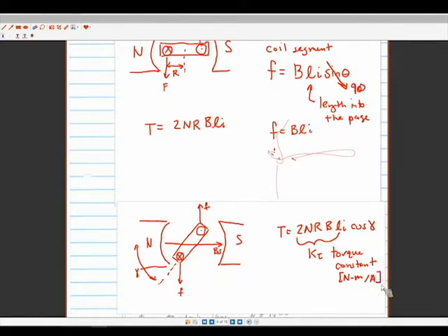Okay, so what the torque constant gives us is basically the relationship for a given motor, it gives us a relationship between current put into the rotor versus torque produced by that rotor, right? So if you look at spec sheets, you'll see exactly on there a torque constant.